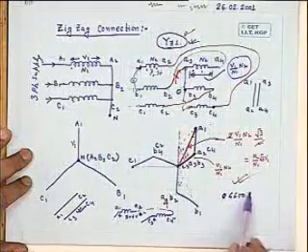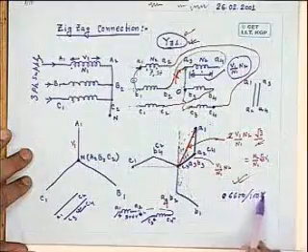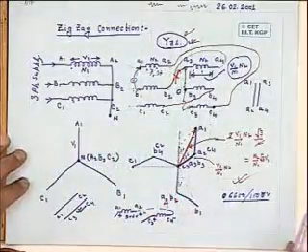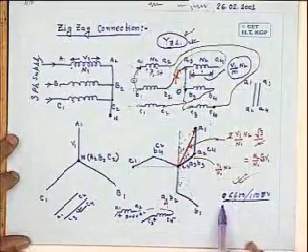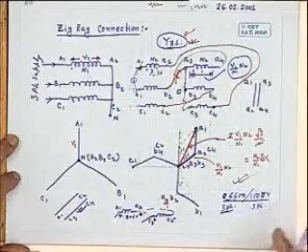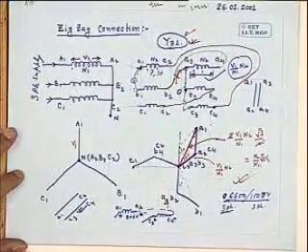Suppose when you compare two things, compare with the same voltage. Suppose the voltage rating is 6600 to say 1000 volt. You just try to compare, same flux level in the transformer. I am asking you a question. Suppose I want to have three-phase line-to-line 6600 volt on the primary, and on the secondary I want three-phase 1000 volt line-to-line. You can do it by a star-star transformer or a star-zigzag transformer. Comment on the number of turns necessary on the secondary side. Same flux level I will be using.